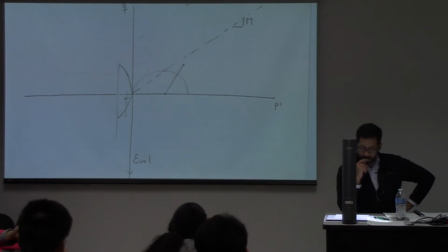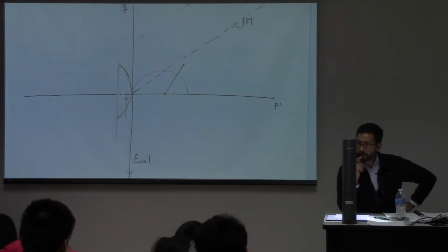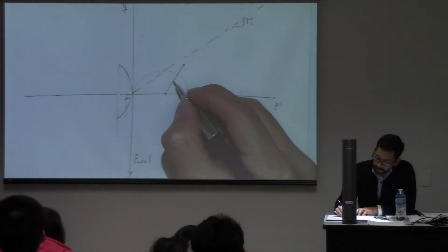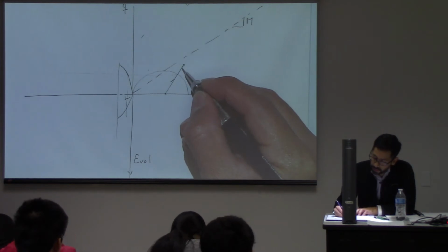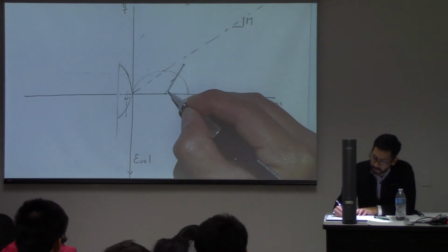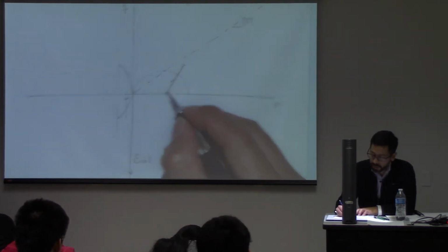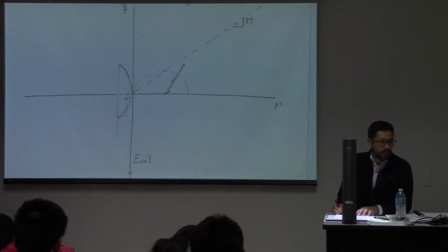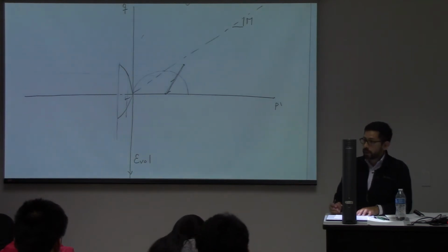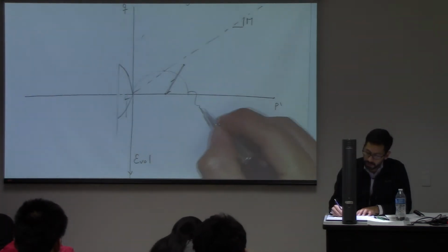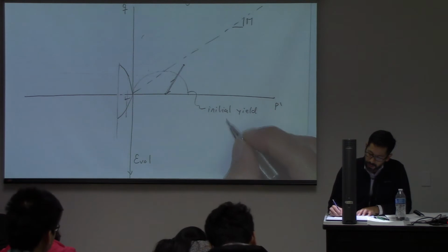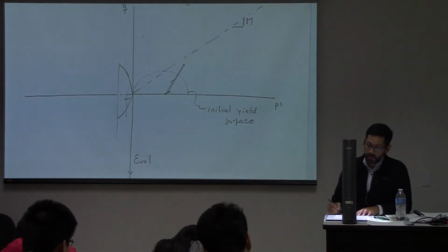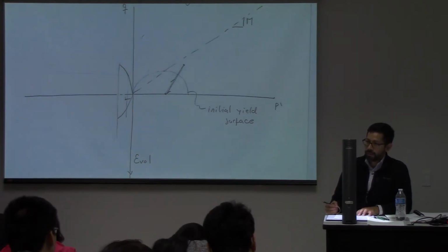All right, so now let's unload the material. So we first loaded this one. Now we're going to unload it back to here, to the beginning. As we do the unloading, because we have gone through this initial yield surface, and because we had some plastic strains, what we're going to get are irrecoverable plastic strains.